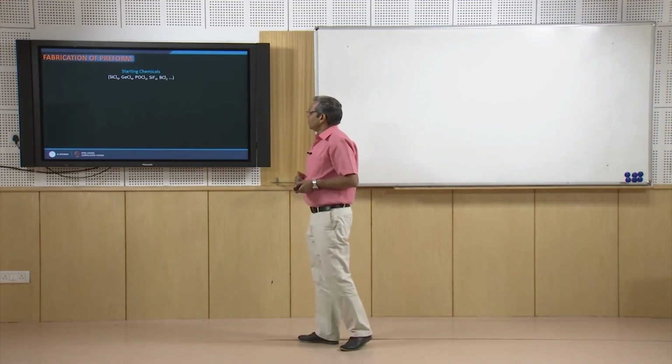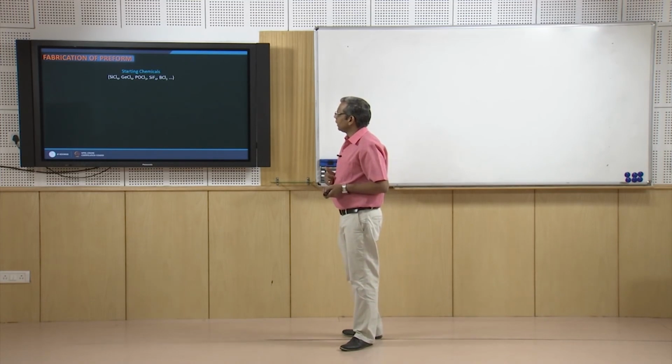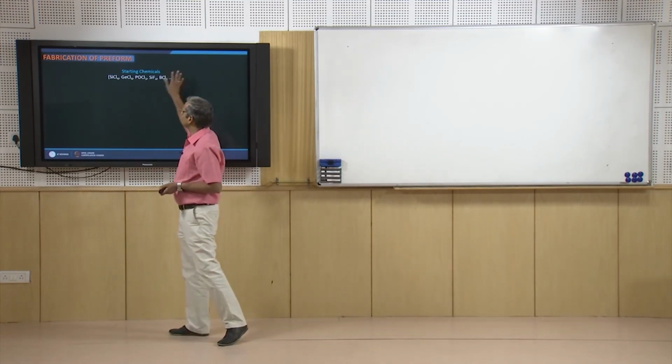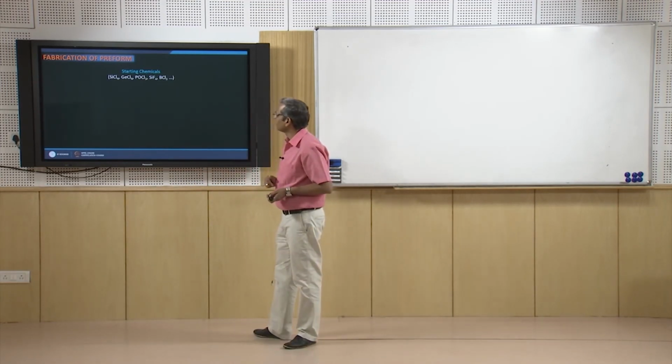When the deposition is finished, then you increase the temperature of burner to about 2000 degree centigrade and collapse the tube into solid preform.